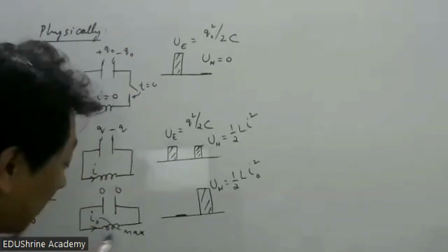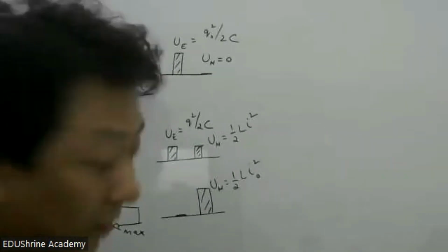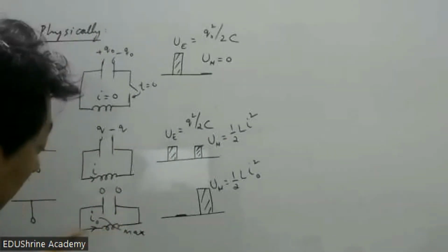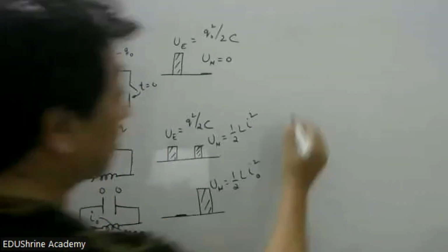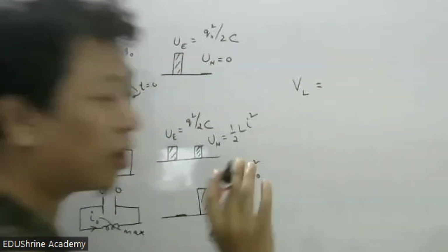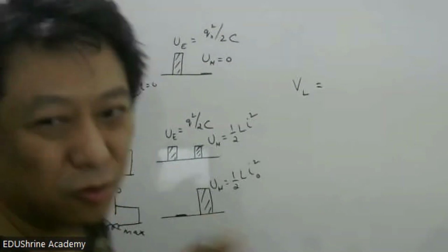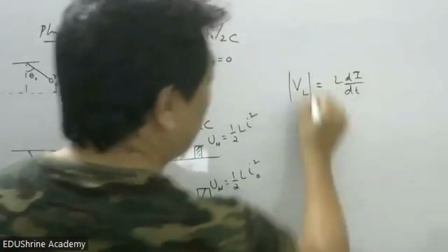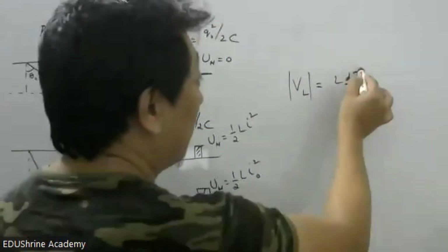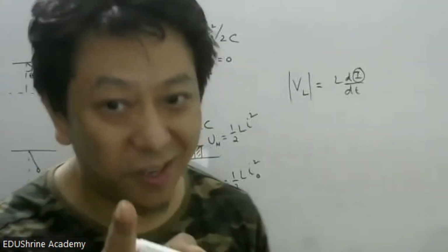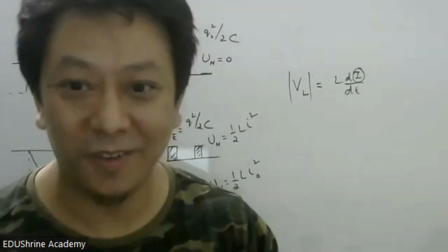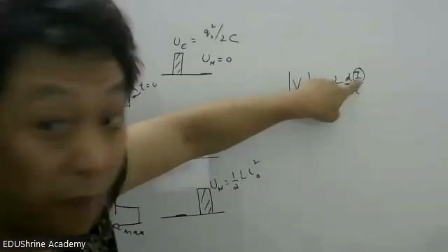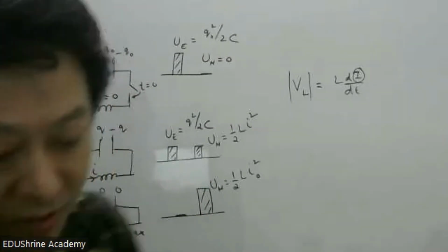Similarly, this inductor we know has inertia, right? So voltage here has become zero. Remember, driving voltage is zero. Current here is maximum, and that is understandable because voltage in an inductor is not I into R, students. It is L di by dt. Modulus if you take. And you all know if current is maximum, what is the differentiation of maximum? Zero. So that's why there is no voltage right now. Even if voltage is not there, there is still maximum current because this is not a resistor. This is an inductor.